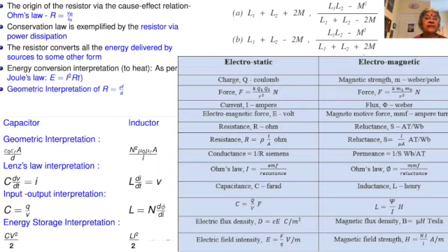the cause-effect relationship. So what is cause and what is effect? There is what is called a magnetomotive force, as given by the number of turns multiplied by the current flowing through the coil, which is giving rise to a flux flowing through the magnetic medium or through air.